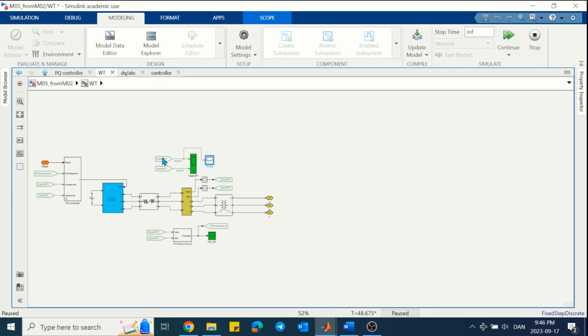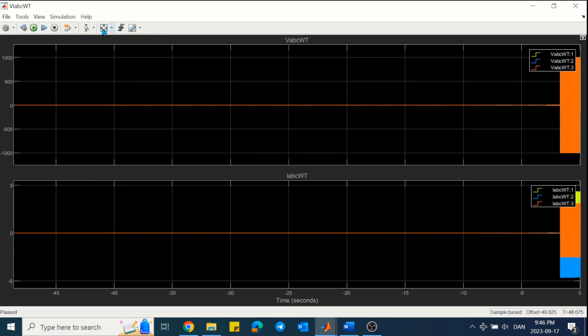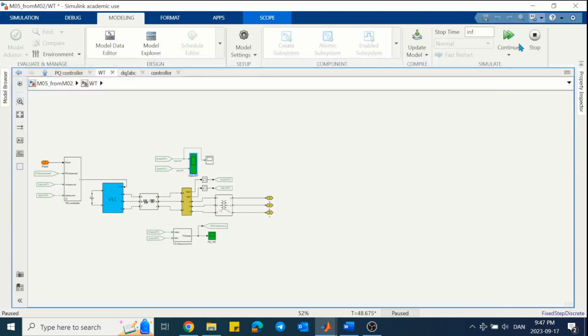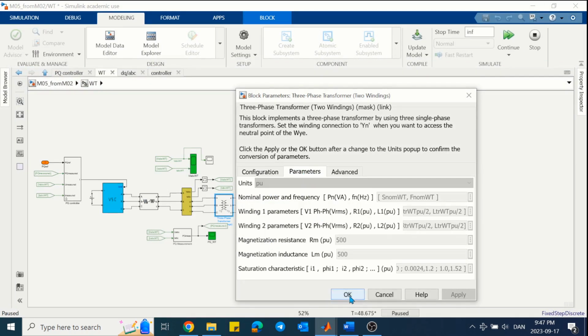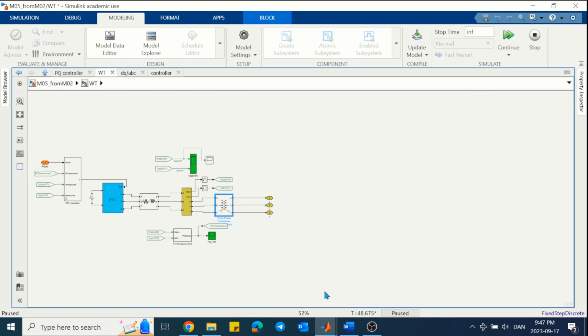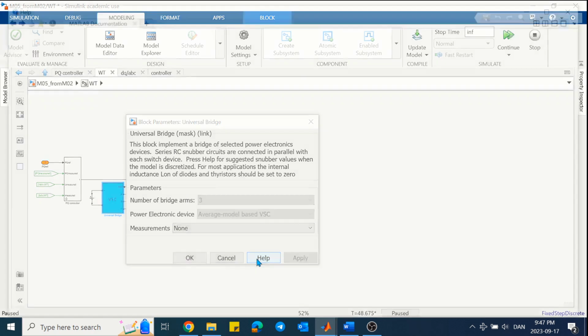In case you are wondering, that is because of the magnetization, resistance, and inductance of the transformer that you can check inside the model. Apart from this, the converter is generating whatever voltage we ask from it, which makes sense, but it is not realistic because in reality converters have some limitations.